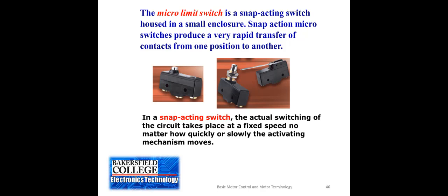Printers, back in the day when we had inkjet printers and printers that would move back and forth on a carriage, one of the things that needed to happen is when you first turned it on, it would move that printing mechanism all the way to the end until it hit a limit switch. Then it knew exactly where the end was, and then that reset the counter that controls the motor location. And then it could go back the correct number of steps and be at exactly the right position.